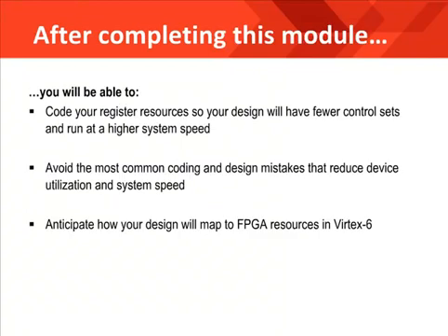After completing this module, you'll be able to code your register resources so your design will have fewer control sets and be able to run at a higher system speed. You'll also be able to avoid the most common coding and design mistakes that reduce device utilization and system speed, and anticipate how your design will map to the FPGA resources in Virtex-6.